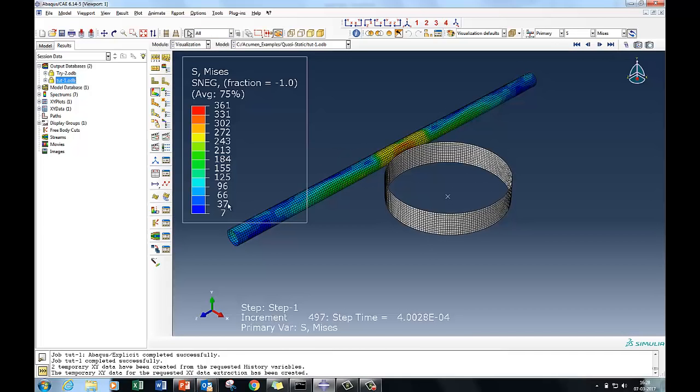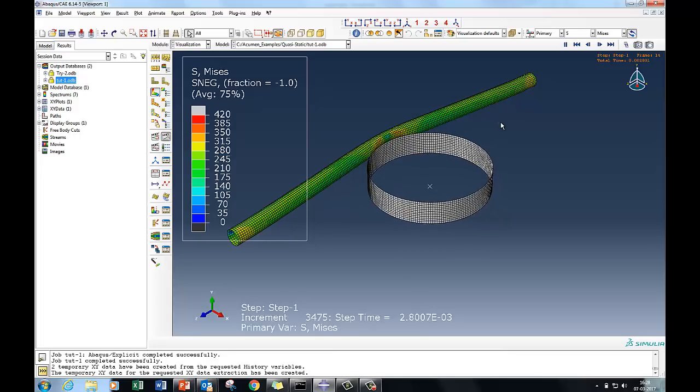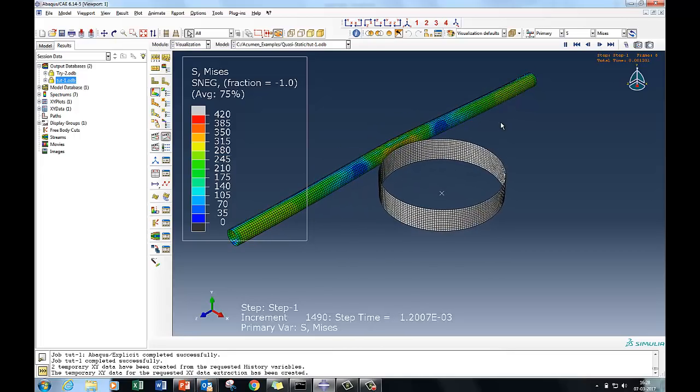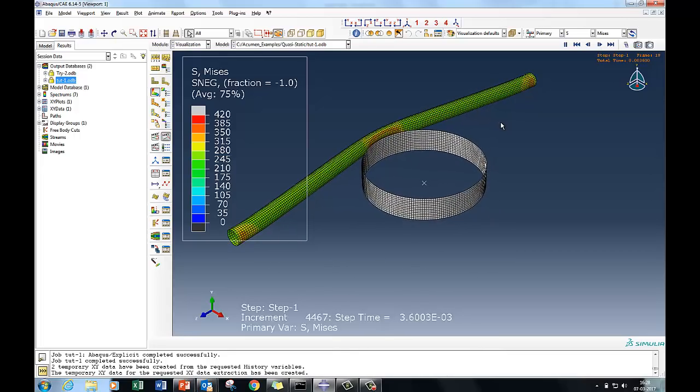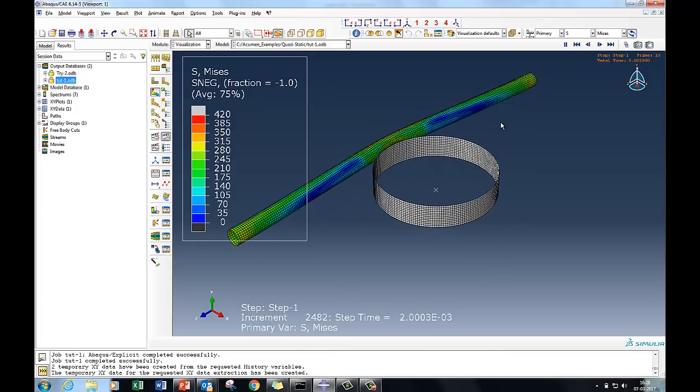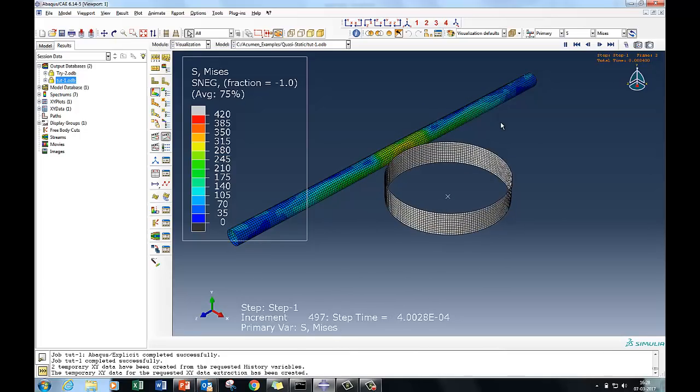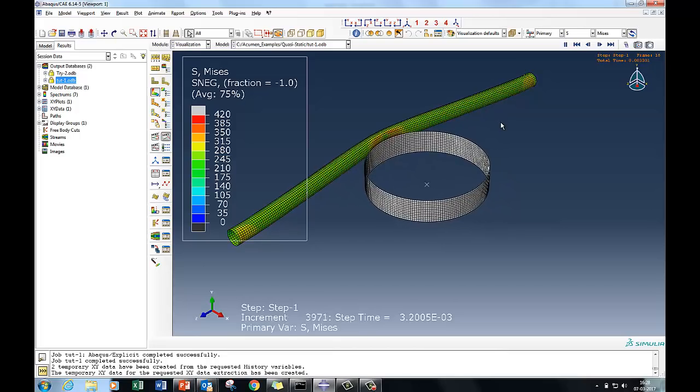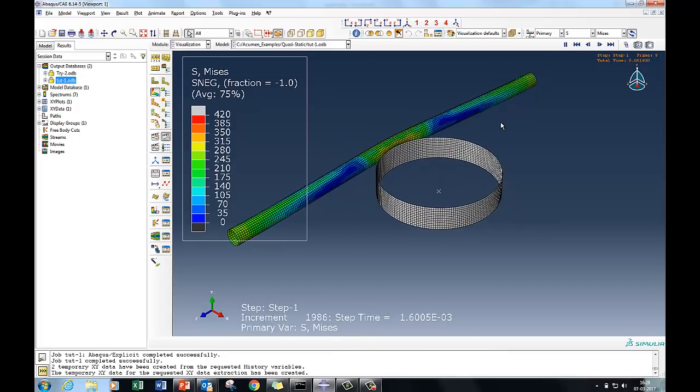So guys, this is what I wanted to show in this tutorial. And as I mentioned, in Quasistatic, that is a slow rate application, so we have cross verified the energy balance curves. The kinetic energy is low and it is stable over the time of application, and the time of application we also found from the frequency, that is the first frequency.